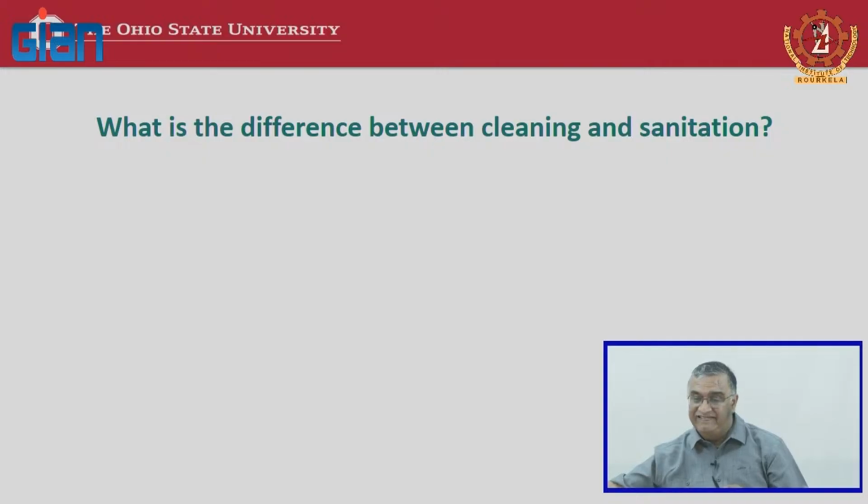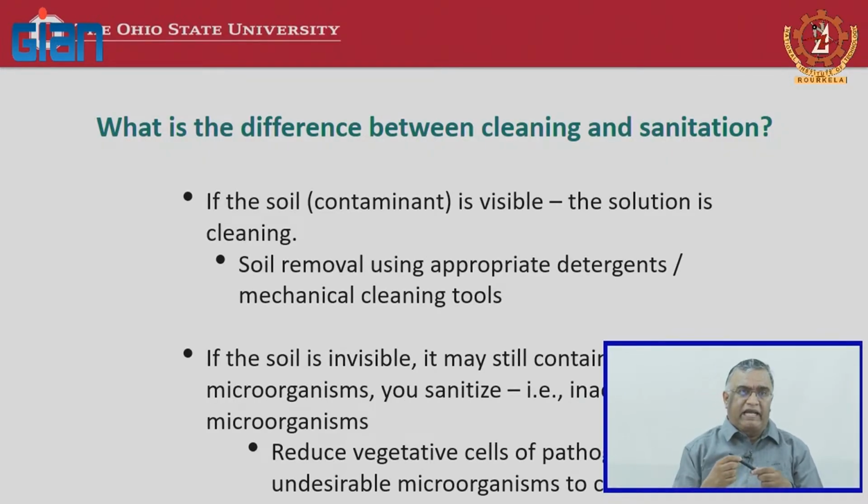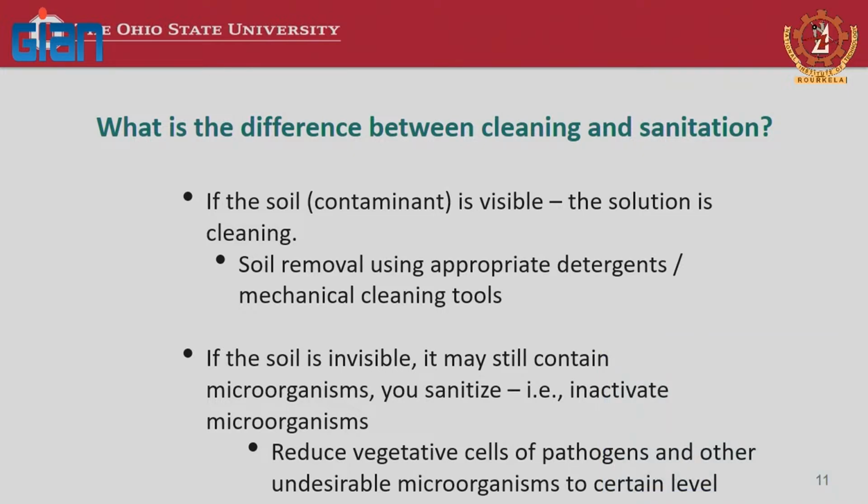Now, is cleaning the same as sanitation? Sanitation basically refers to getting rid of the microorganisms to a certain target level, whereas cleaning primarily refers to removal of the residues, your protein films, things of that nature, during the process. So, the soil is visible, and then you clean it. On the other hand, once you clean it to the extent possible, there is still a possibility of microorganisms attached to the surface, even though the surface looks visibly clean.